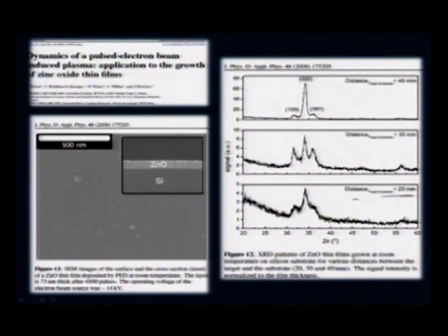If you keep the distance at, say, 2 centimeter, then you are seeing these 3 peaks, which are characteristic of zinc oxide, to be more broader. In other words, it is more amorphous. If you keep it at 3 centimeter distance, then the crystallinity improves, and the best samples are made when the critical distance is at 4 centimeter. Therefore, each system has its own sensitivity. We need to optimize that distance.